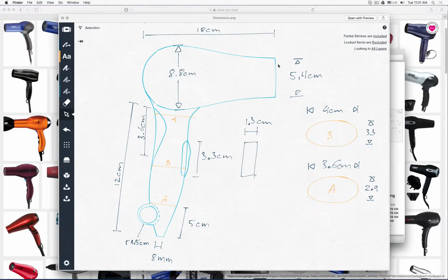And you see I basically only capture, for example, the width or the length of the upper tubular body, the diameter of the front opening, the diameter of the widest or thickest area, the length of the handle, the length of maybe how far the surface cut will be, the radius of the ring, the diameter of the cable outlet, maybe the length, how far the cable starts to blend into the main body. And then here you see A, B, and A. These are actually cross sections.